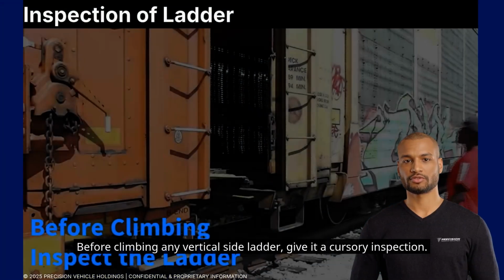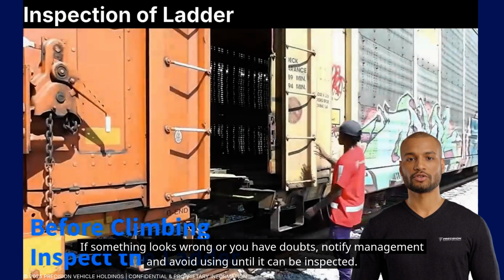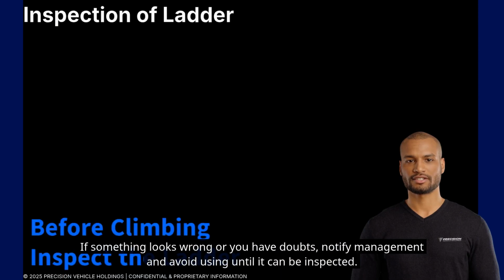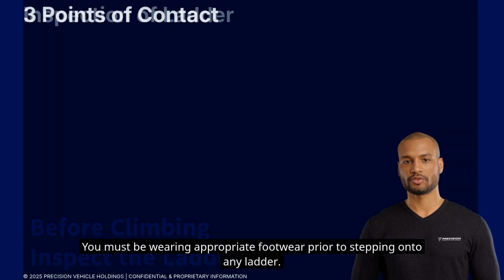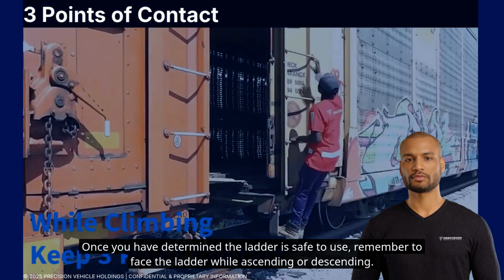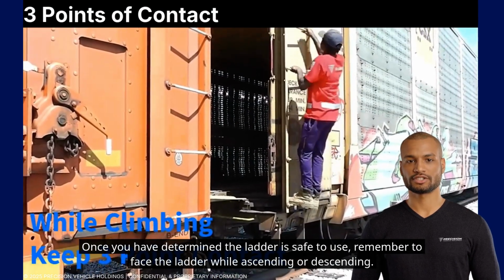Before climbing any vertical side ladder, give it a cursory inspection. If something looks wrong or you have doubts, notify management and avoid using it until it can be inspected. You must be wearing appropriate footwear prior to stepping onto any ladder. Once you have determined the ladder is safe to use, remember to face the ladder while ascending or descending.